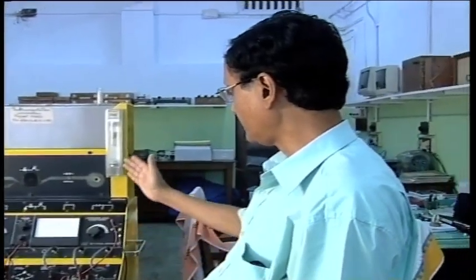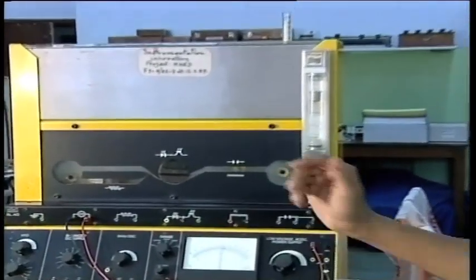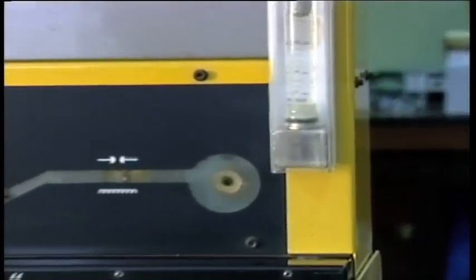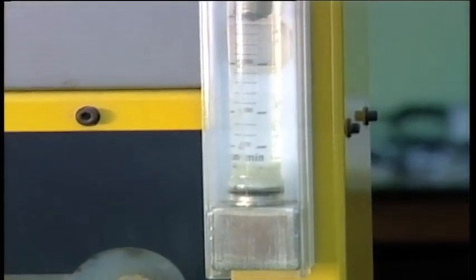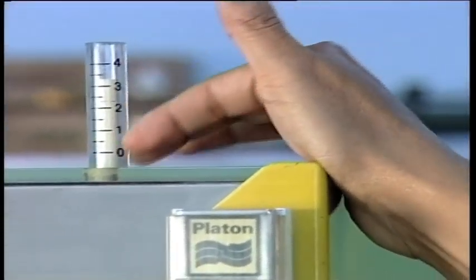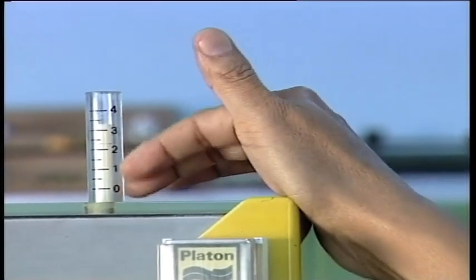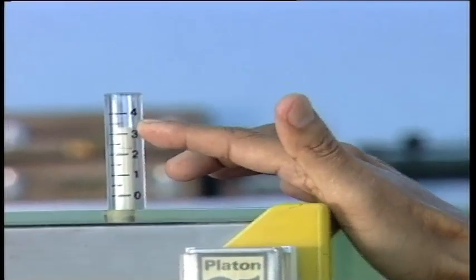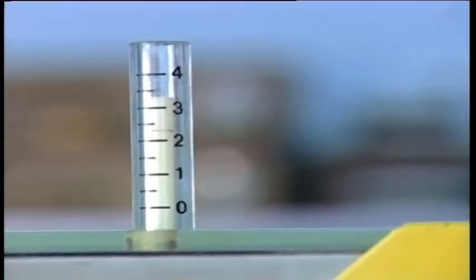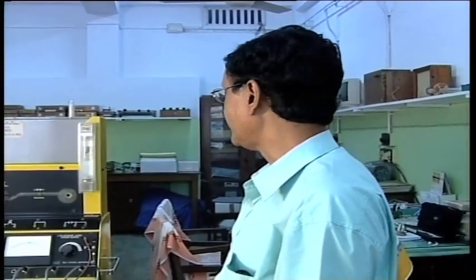There are rotameters, there is an optical flow meter, there is a hot wire anemometer, and there is also a magnetic flow meter. On the top of it you will find a weir, which is called a V-notch weir. As you know, flow meters are of different types. Some of them are for the open channel and some are for the closed channel. This V-notch weir is basically an open channel meter, extensively used for irrigation purposes, so that you can estimate how much water is needed in different fields.